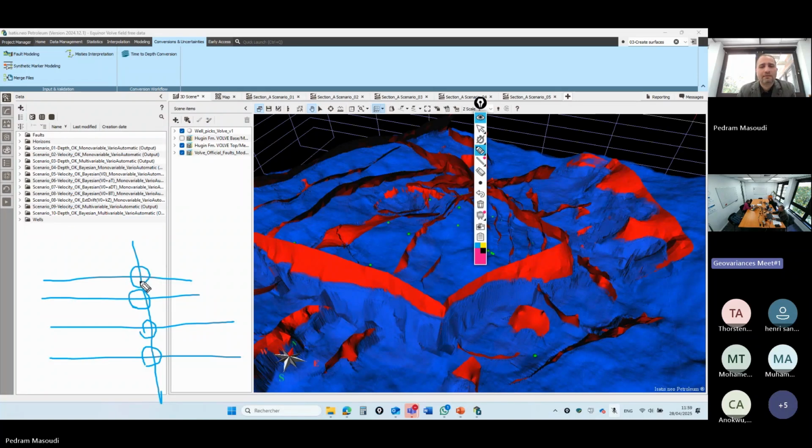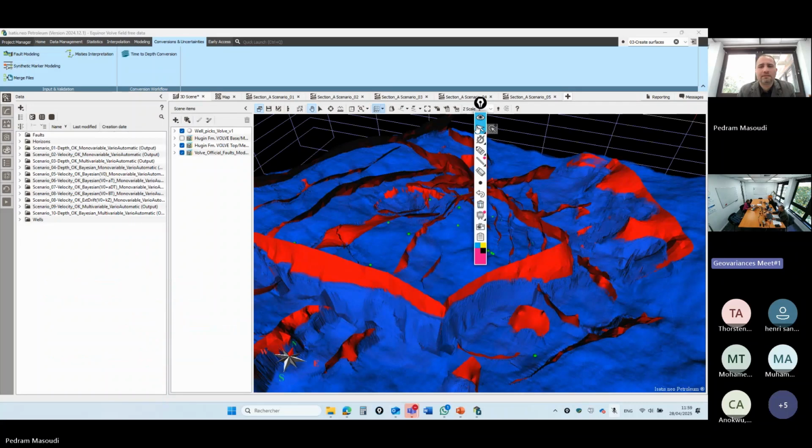But applying this method adds some measurement error to those measurements that have high discrepancy, and lower measurement error to those with good compatibility between inline and crossline. So it will reduce the artifacts where we have higher differences between the crossline and the inline. It's a tiny statistical correction, which is available in Isatis.neo.